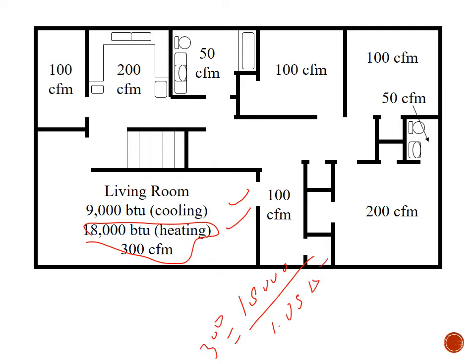I want to see what my delta T is. So what I would do is multiply that 300, equal, and divide 1800 over. So here I got a delta T. If I solve for delta T, I'll get a delta T of 60 degrees. So probably we have the room at 70, and my temperature will be 70 plus 60, which is 130 degrees.